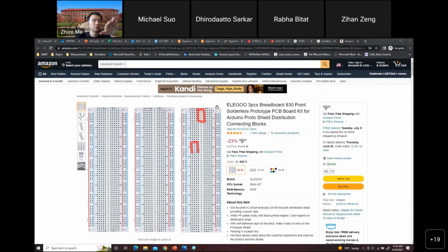let's say right here, what will happen is you're shorting the pins that are in the same row, because if you remember, on the breadboard each row is shorted. Make sure your chip is on the gap in between. That's the first thing you want to pay attention to.